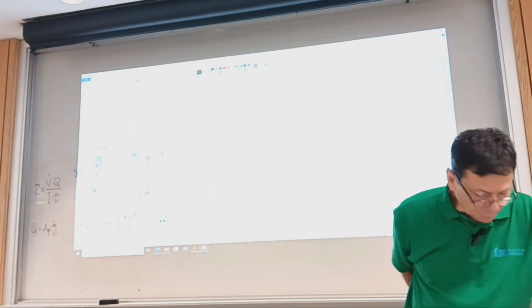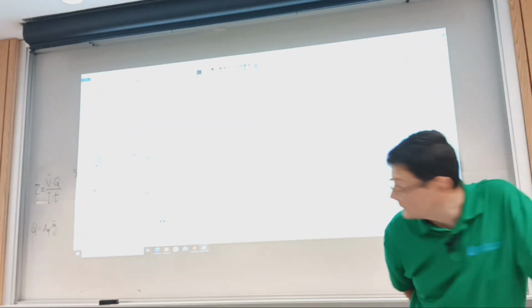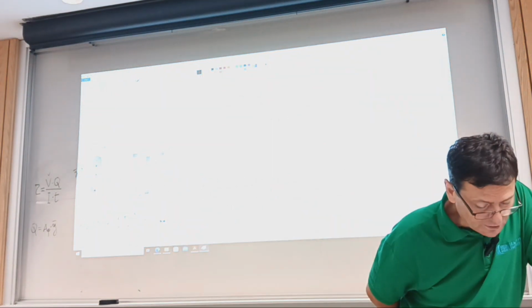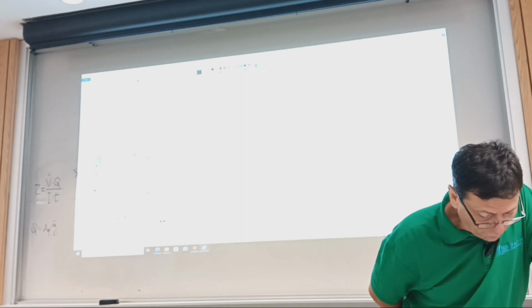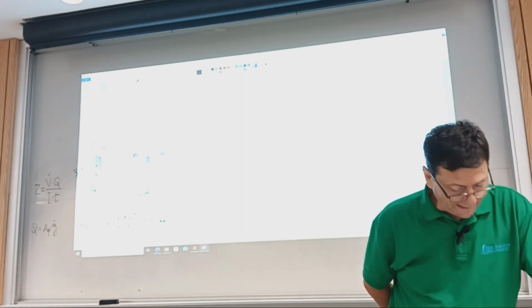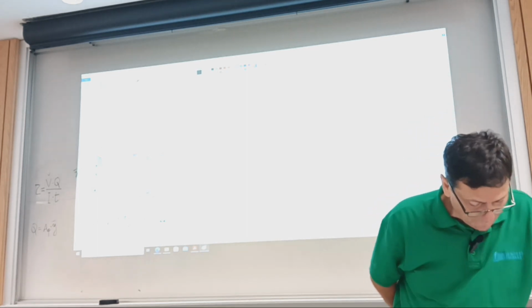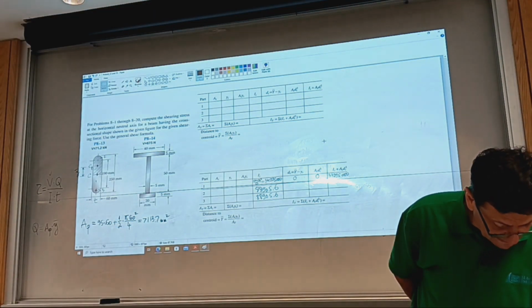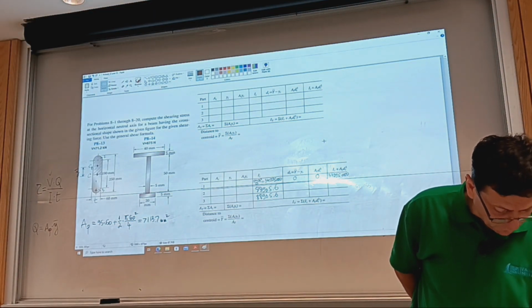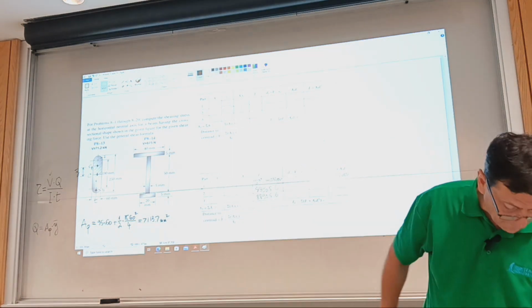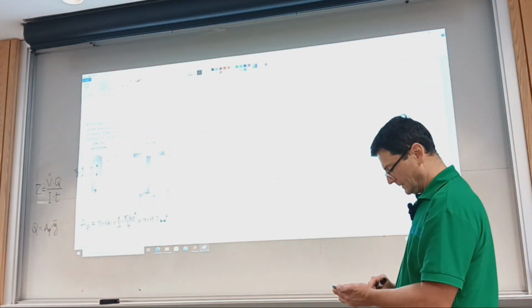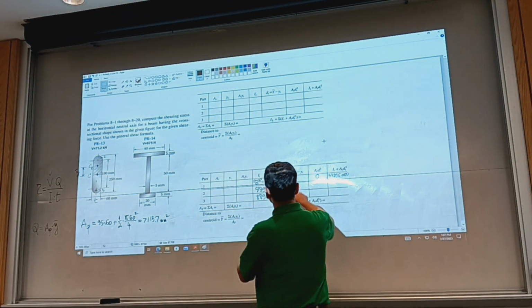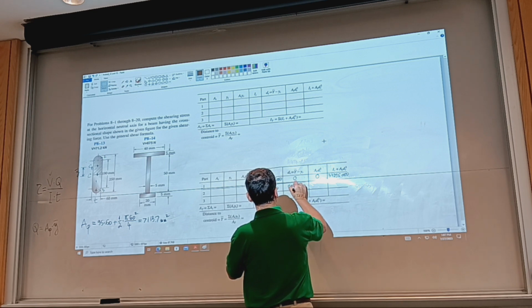So we need to look again at page 754. The distance from the base of the half disk to the centroid says here 2/(3π) times diameter, or 0.212 times diameter. 0.212 times the diameter of 60 is 12.72.